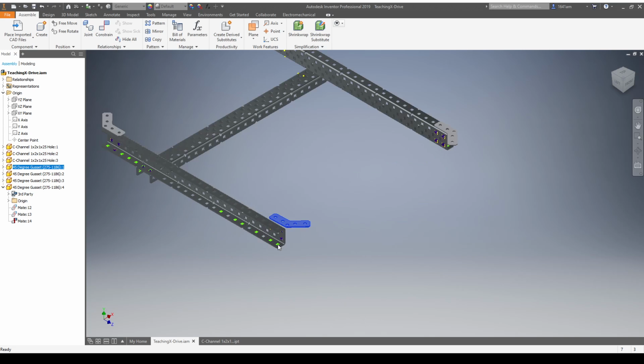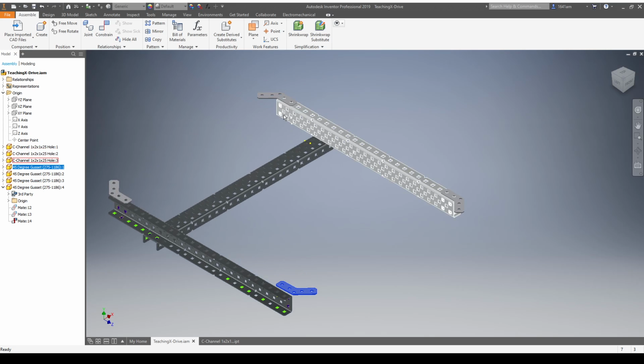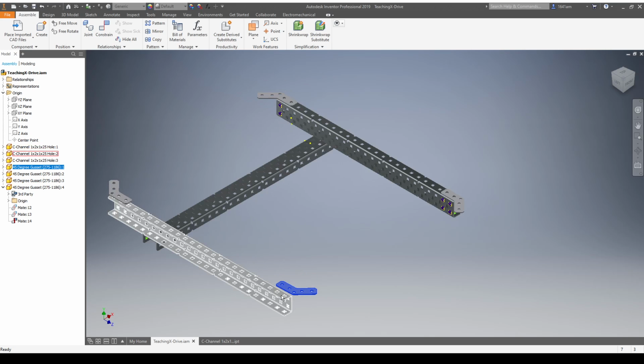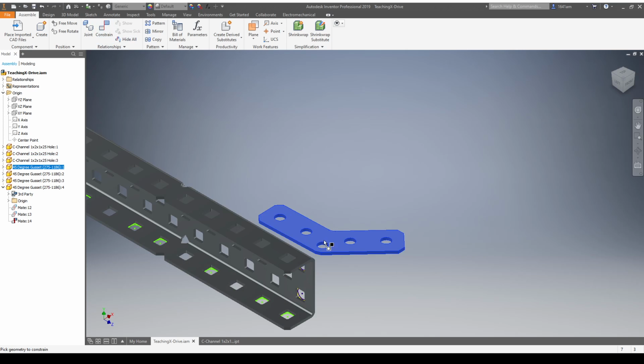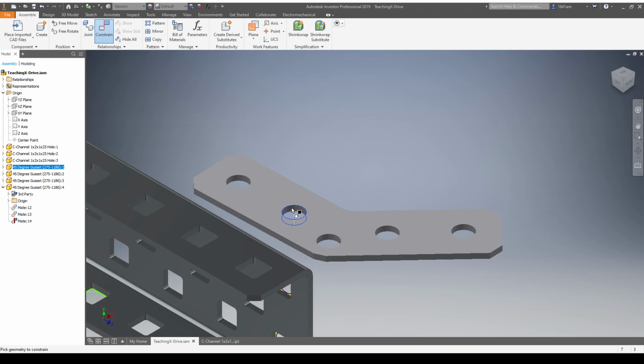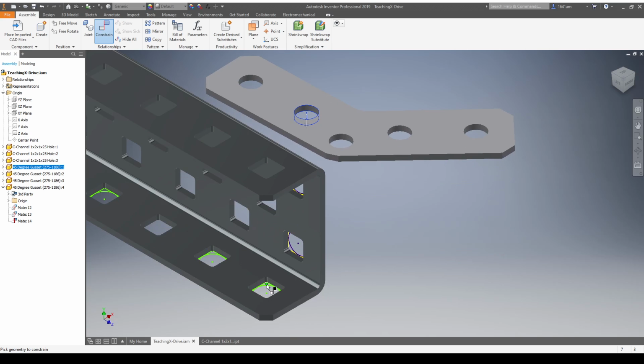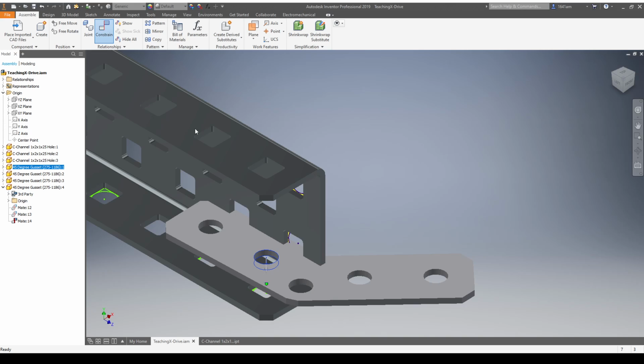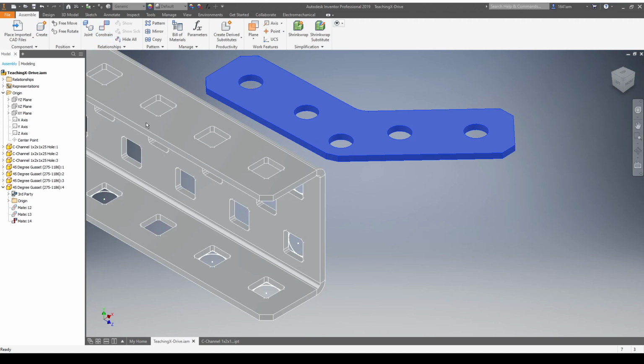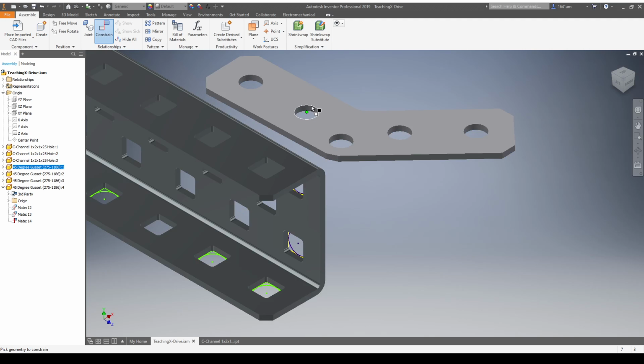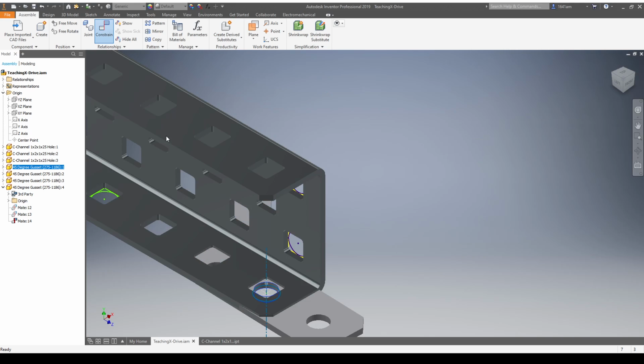So we already have the circles here because you should have drawn the circles over there and these two pieces are reversed. So constrain, pick the inner axis. Oops, I clicked the wrong thing. I clicked a corner instead. So what I can do is just click cancel, constrain. Make sure I click the axis this time. Make sure you click the one without any arrows that says undirected.